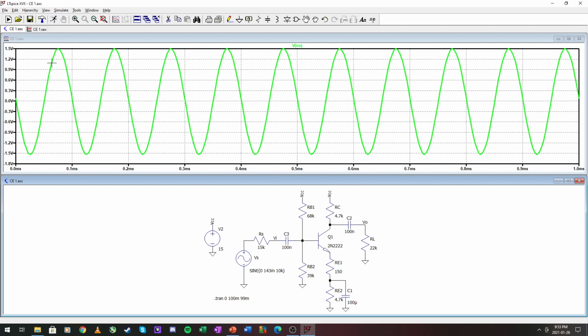Okay, it's not as bulky on the sides anymore, and it gets to 1.5 volts peak, where we calculated 1.43 volts peak. So yeah, this amplifier is much more linear than the others. For higher input range, lots of degrees of freedom, and that is why this is one of my favorites typically to ask people to design.